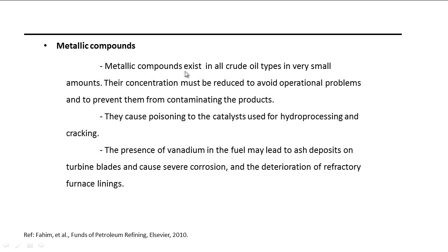The metallic compounds are present in all crude oil types, but not in very high concentration, and they must be reduced to avoid any operation problem and to prevent them from contaminating the product. Not only that, metallic compounds can poison the catalyst in any hydroprocessing and catalytic cracking.